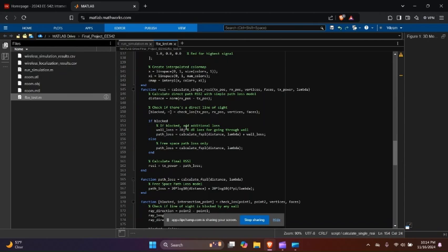Especially if there's a metal rack, which we have modeled, there would be complete reflection. So many reflections. So it's not just a simple path loss equation that we are blindly formulating. It's a path loss equation that understands the geometry of that particular place in which it is operating. Okay, so that is what we did.